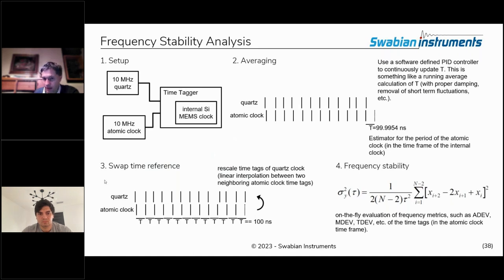And maybe to go beyond that: in this particular example, I've just talked about a periodic clock signal. This could also be clock recovery from data where you have missing edges or stuff like that. Because it's completely software defined, it's very easy to implement very complex clock recovery from whatever funny signal, and then measure frequency stability relative to that signal or of that signal.